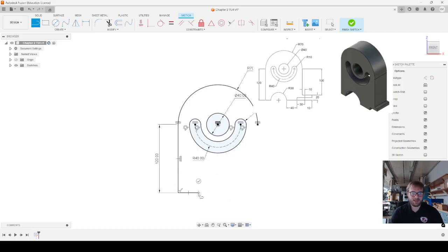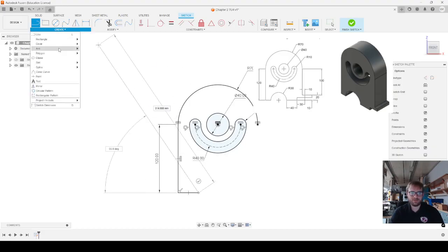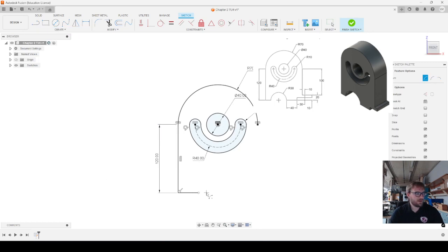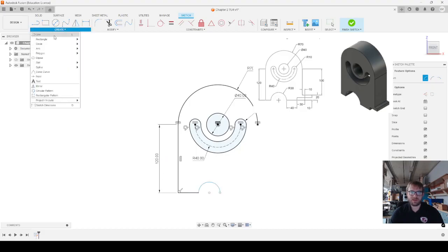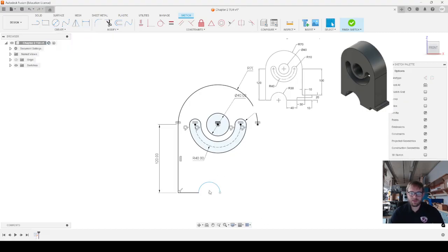It doesn't say because I was doing it the other way from what they told me. Here I could do the center point arc, and notice how it wants to show this little dotted blue line here. That's great. I can do that and come up and around. I could also do it with the 3-point arc tool. So that's handy. Okay, so now I know that that radius, D for dimension, is 30.